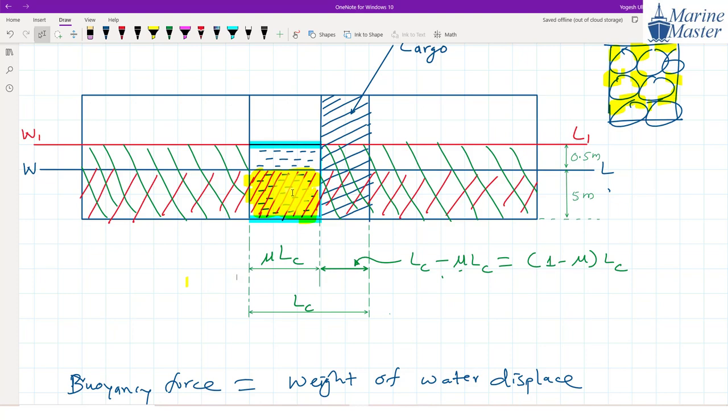So now, guys, what is happening here? In this portion, displacement will be equal to buoyancy. So if you want to maintain a displacement, whatever loss we are getting from the buoyancy, we are basically losing the buoyancy in this region. In this region, what is happening, guys? That I have highlighted in yellow. Loss in buoyancy. So there is loss in buoyancy.